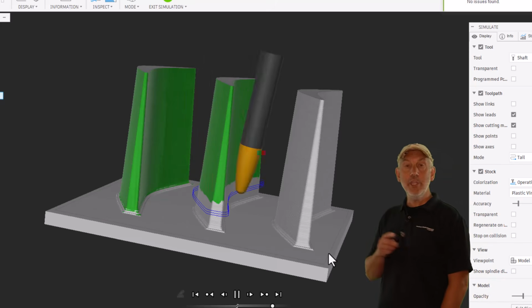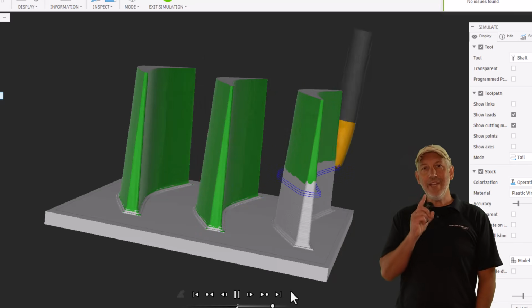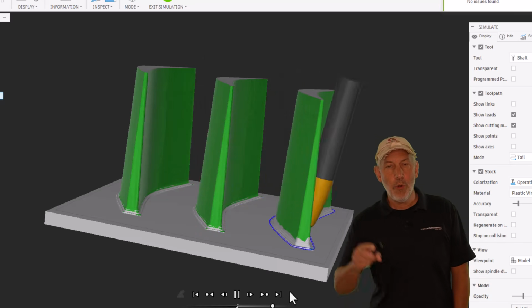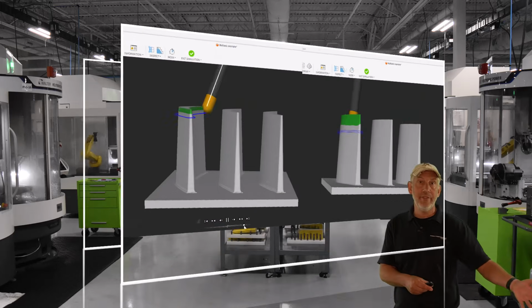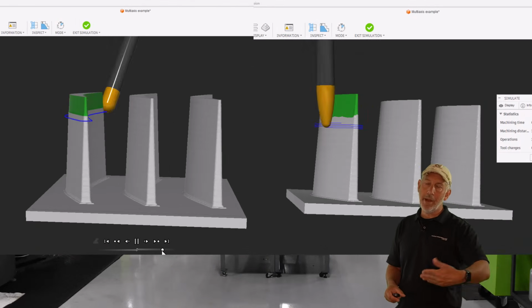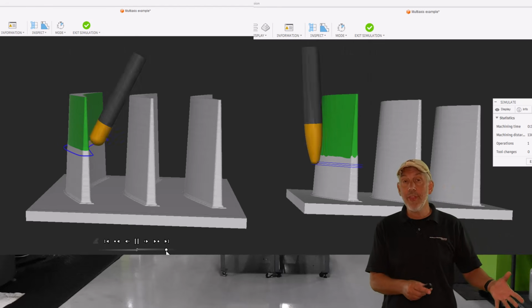So now we can use an oval form. We can run this tool. We can create a very easy toolpath with an oval form. We can cut very easily and we can save a lot of time. Now just look at these. Let's look at these side by side. We used a ball nose before, the 10,000 step down. I actually think you're probably going to have to step it a little bit closer to get your RA. But we used a 10,000 step down.